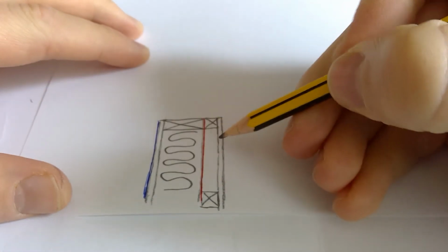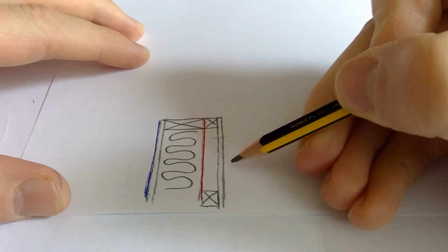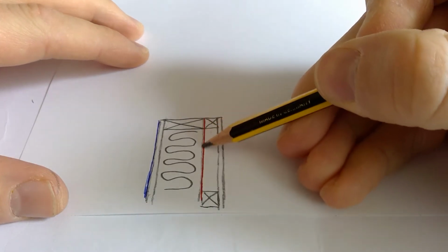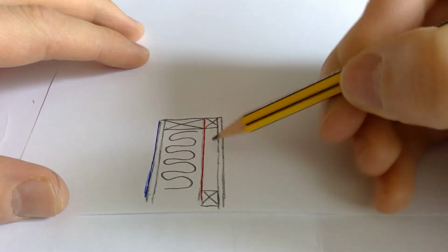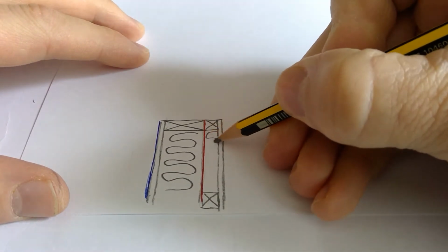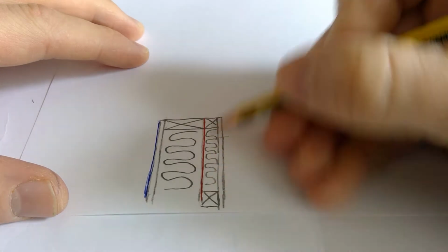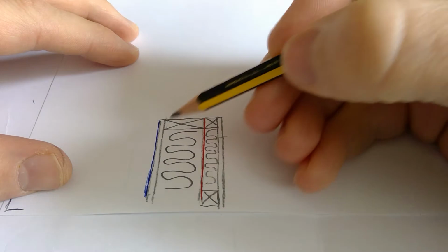Now the idea of that is, if you want to drill a hole in here for whatever reason, hang a picture or put up some wires or whatever, you're not penetrating the air tightness layer, so you're not compromising the air tightness of the house. That's why you have a service cavity. Service cavities always have some extra insulation in there as well. So it's basically a couple of battens sticking up and then plasterboard over, and they can plasterboard onto that.